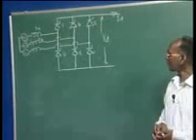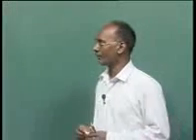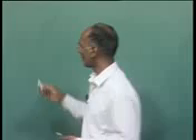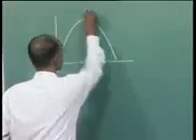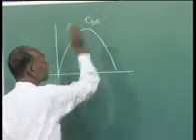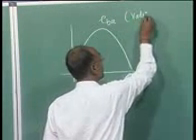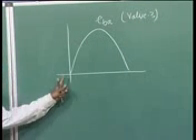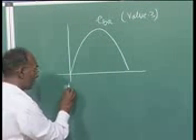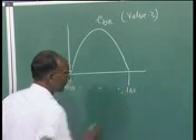Now in the inverter operation, what we do is delay the firing angle. As I said, the commutation voltage of valve 3 is EBA. This is the commutation voltage of valve 3. Here, valve 3 means this valve will be fired if the gate pulse is available. From here alpha is 0, and we can go up to here, alpha is 180 degrees.